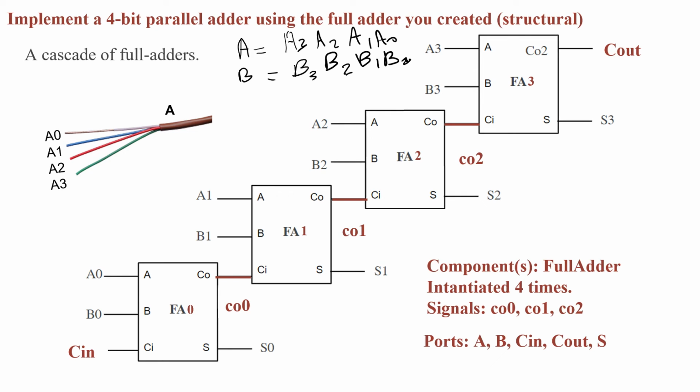And so far we've only learned how to express if a variable or if a port is a single bit. Here A, B, and S are ports consisting of 4 bits. And the way we can express that is by saying, instead of standard logic, we'll say standard logic underscore vector. This specifies that it's more than a single bit. The signal is more than 1 bit.